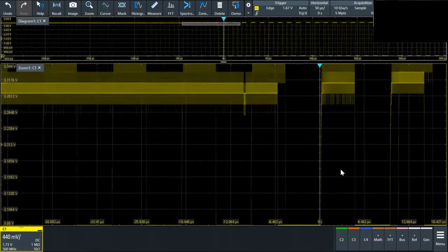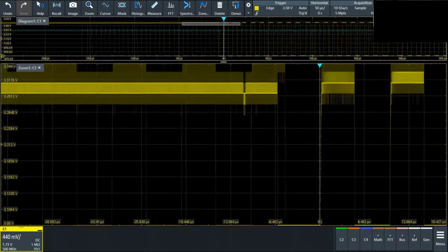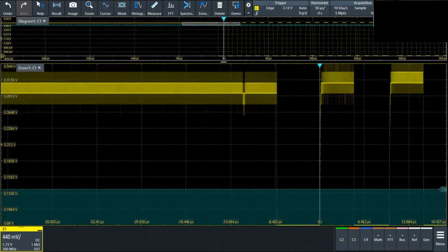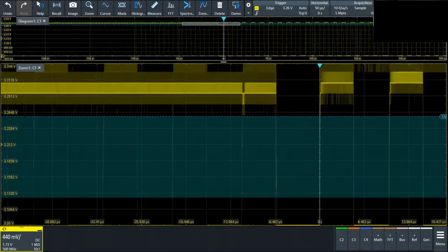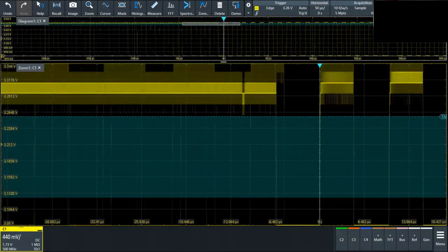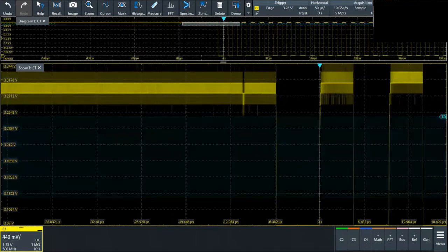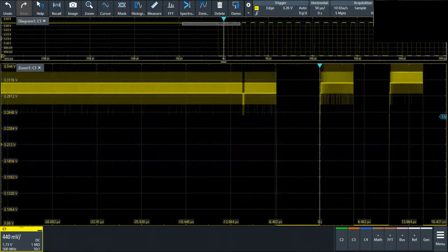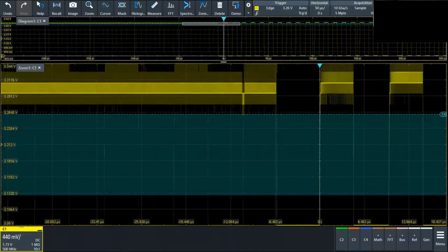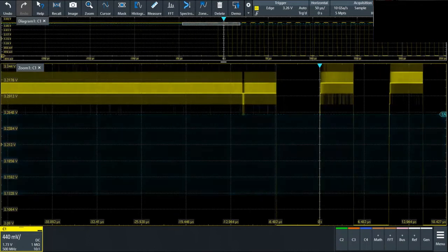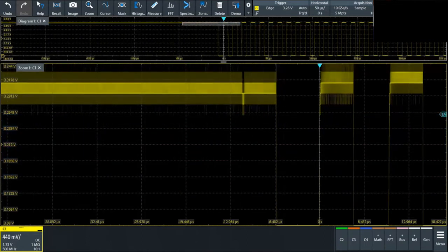And you're going to say, how do you do that? Well, basically bring the trigger up, and here comes the trigger. One of the interesting features of our trigger is that little band there. That's a hysteresis band, a noise rejection feature. If the signal enters that band, it triggers when it exits that band. The problem is right now I'm at the resolution limit of the scope, so I really can't do much to trigger on that because I can barely resolve it with my A to D converter. On a typical oscilloscope, you're kind of dead in the water here because there's no way you can get that better. You can filter it, but the trigger doesn't see the filtering.